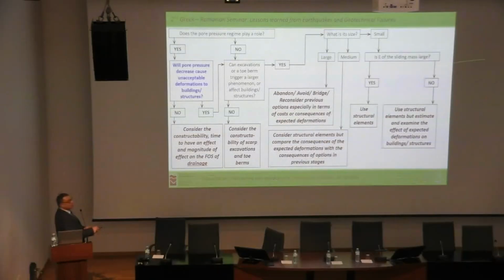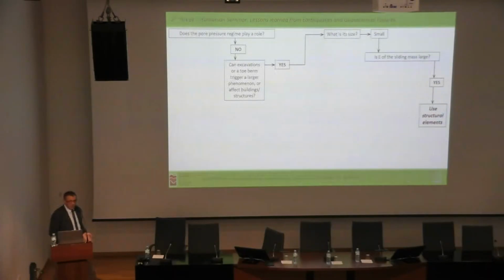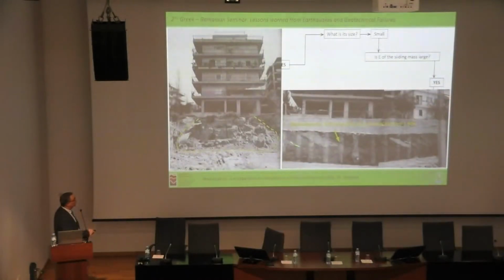And here I have again only two examples. Does the pore pressure regime play a role? No. Can excavations trigger something larger? Yes. What is the size? Small. Is the modulus of elasticity large? Yes. Use structural element. Here it is. A structural pile wall that was used there in order to stabilize this and the adjacent block of flats.